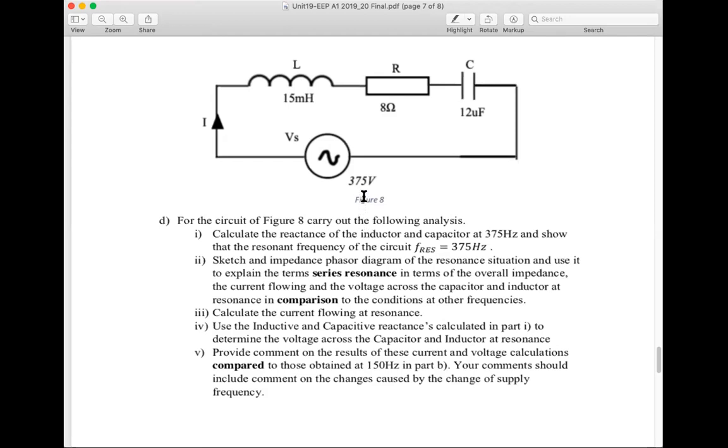Yeah, but remember, because you're inputting 375 volts and you're getting thousands and more volts across the components. But remember what resonance means. I don't really know what it means. You do know. Well, remember, any circuit like this has a particular frequency that would be its series resonant frequency. And at that frequency, the size of the reactance of these two components, L and C,